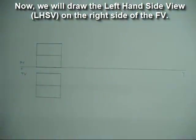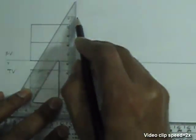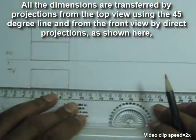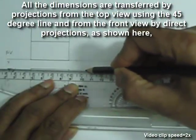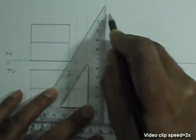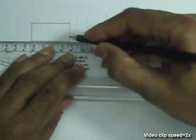Now we will draw the left hand side view on the right side of the front view. So this is another reference line x1, y1, and we draw a line which is 45 degrees to the reference lines, and we will project all the dimensions from the top view up for the left hand side view. So using the 45 degree line we can project the dimensions from the top view for the left hand side view, and from the front view we can directly project the dimensions.